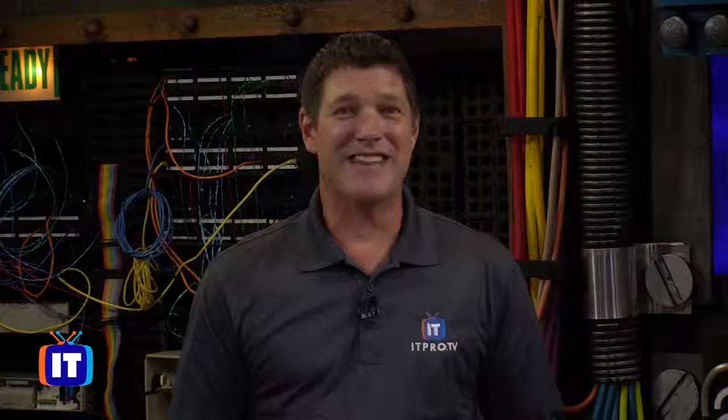All right, Wes, so I'm going to have to ask the obvious question. Type 1, 100 pins. Type 2, 100 pins. There has to be a difference, though, right? There really is. What it came down to is what the manufacturers implemented them for. The most common one was really the Type 2, and this would add network functionality to a laptop that didn't have it. So you'd put one of those Type 2 cards in there, 100-pin card, and you'd have like this little X jack that would pop out, and you could put a modem, like one of the old RJ11 jacks, or as we progressed, you could actually add Ethernet capabilities, which we'll talk about, the Ethernet connections, in another episode.